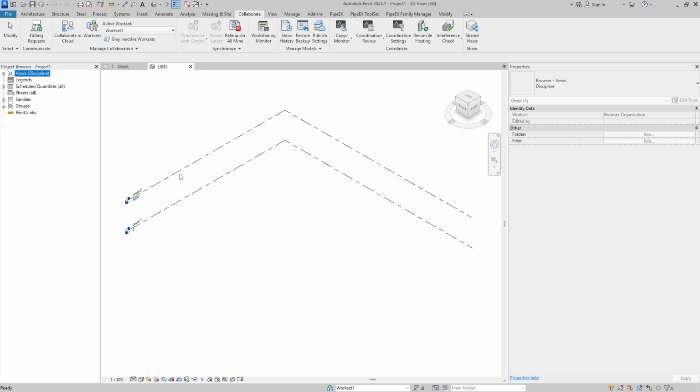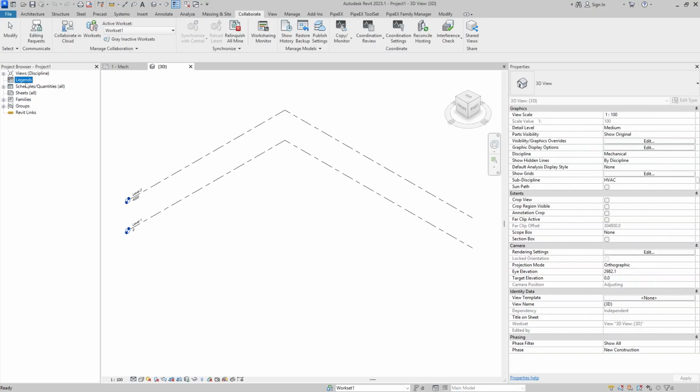Of course, depending on the organization where you work, it can deviate from what I said, but I would say that you always must have these 4 extra parameters that are related to views, schedules, sheets, and, well, legends aren't actually included in this list, so you can forget about it, because legends aren't really relevant for what we are going to do. I would say because it will always be plain, so you cannot do much about it.